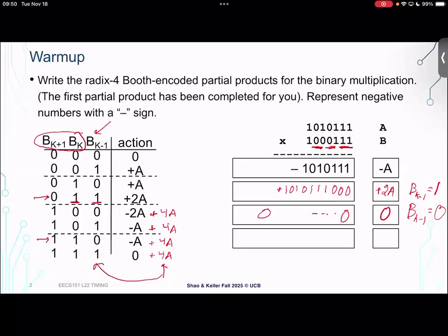Now, we do still occasionally get zero partial products when we Booth encode, right? It's like a 1 out of 4 chance instead of 1 out of 2 chance. Okay, so then once again, we have no +4 coming from the previous group. So our b sub k minus 1 is 0 for this last row. So it's just a 1, which is sort of implicitly a 0, 1.